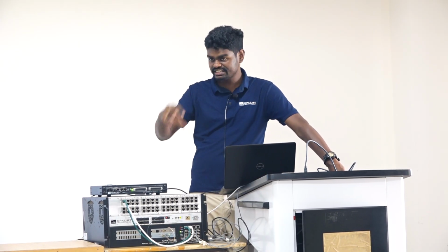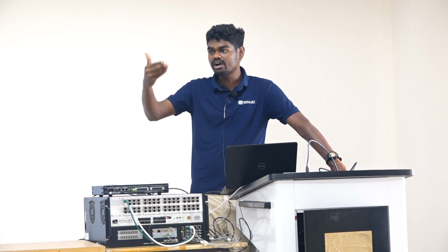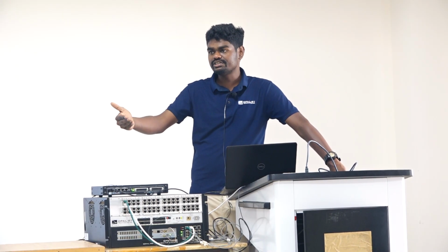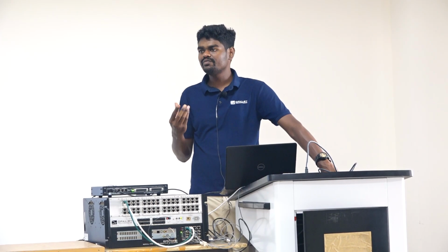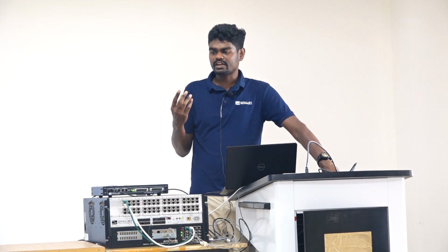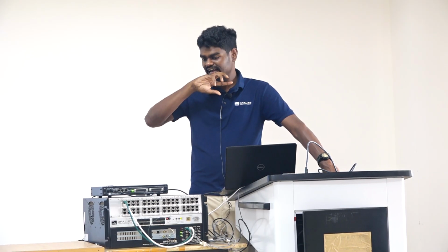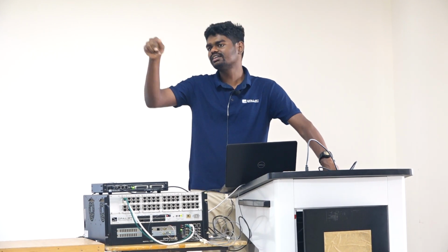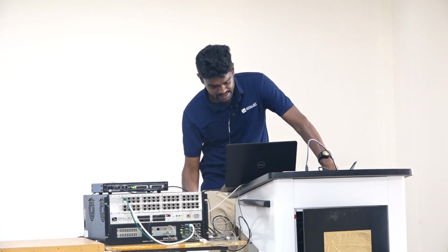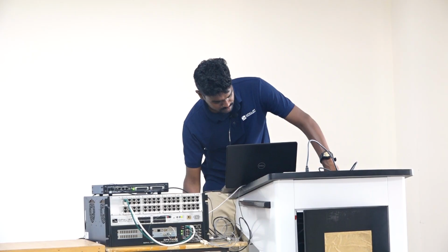Now to run it in this controller, you need to additionally configure the analog inputs here on the controller. That means ADC. You need to configure ADC modules in the controller. ADC is the one which helps you to configure the analog inputs of the controller, and it will help you to bring the signal which you have outside into the controller. So you can see the ADC modules here.